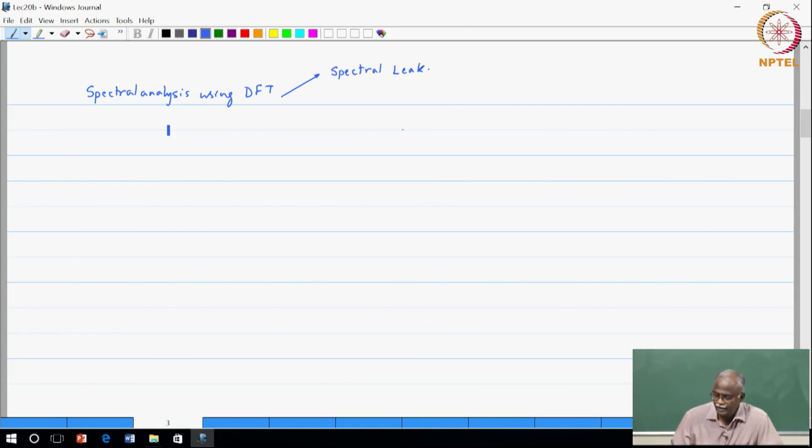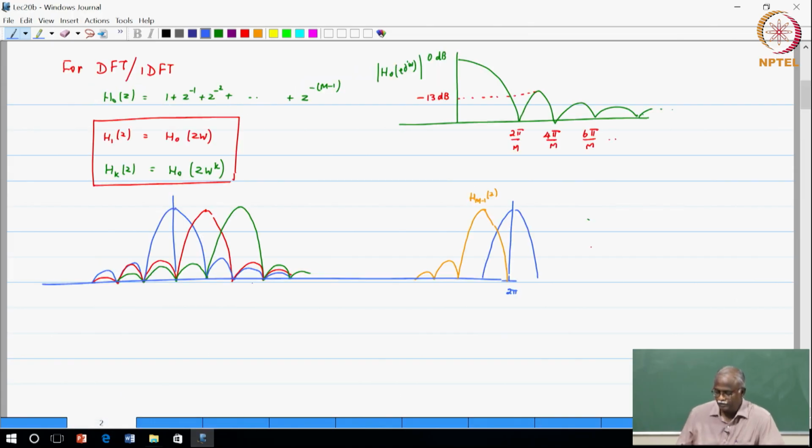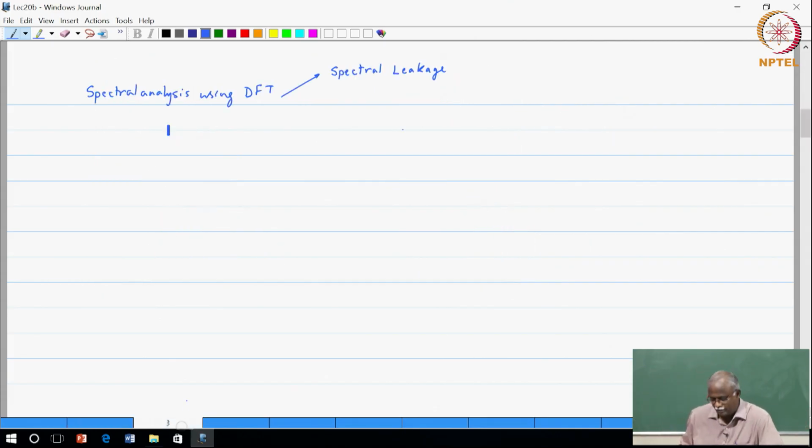So, you can get some misleading interpretations, and it goes back to your filters not having just a passband, but they have got kind of ripples. So, therefore, you can get some erroneous conclusions. To improve upon this, we use windowing. Without windowing, it is not a good idea to attempt the DFT.